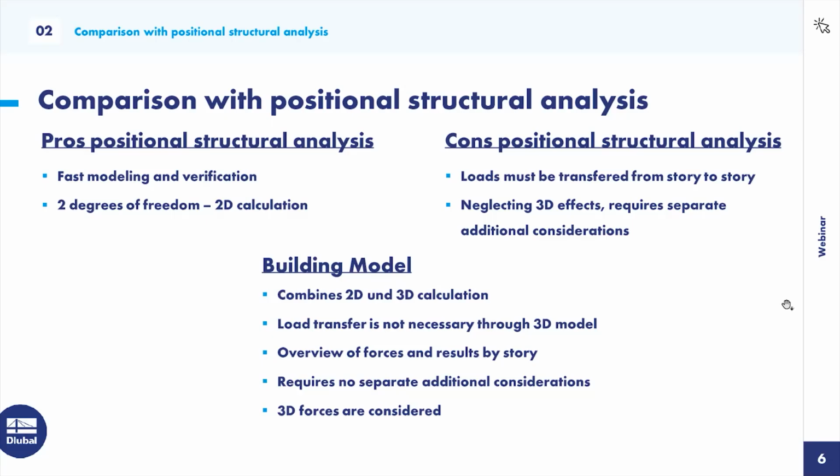Okay, another con is that this 2D calculation neglects 3D effects, and for example some forces, let's say torsional moments, and you also need separate additional considerations or additional checks which are for the whole building.